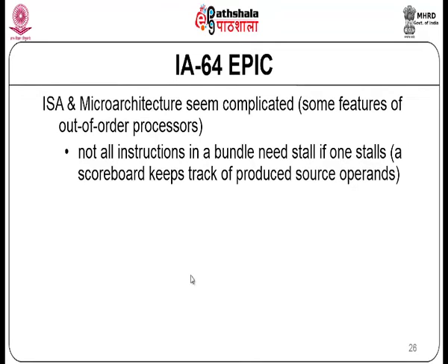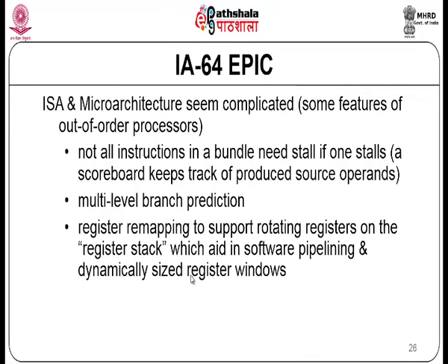A scoreboard, which is similar to our Tomasulo's dynamic scheduling algorithm, keeps track of dependencies between the instructions and when the source operands are produced for the dependent instructions. You have multi-level branch prediction support, extensive support for predication, and what are called rotating registers to support software pipelining.